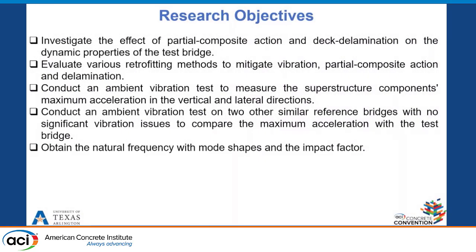The current research investigated the effect of partial composite action and deck delamination on the dynamic properties of the test bridge. In addition, various retrofitting methods to mitigate vibration, partial composite action, and delamination were studied. Therefore, this study could be a benchmark for future studies on dynamic evaluation and retrofitting of partial composite action induced vibration of prestressed concrete girder bridges.